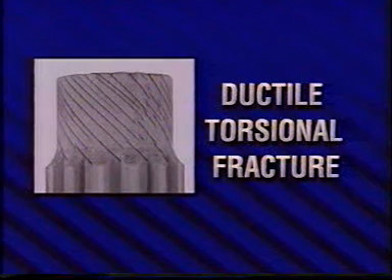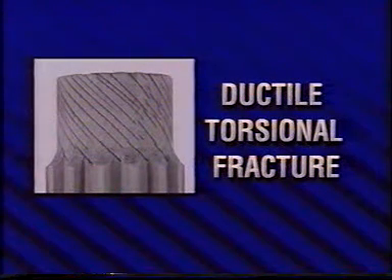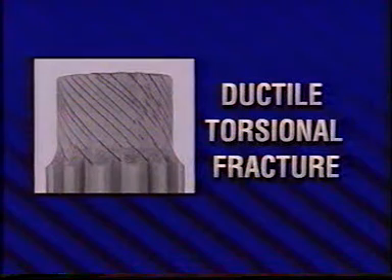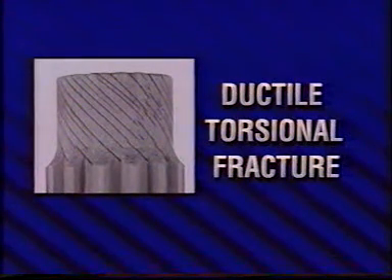Shear stresses are longitudinal and transverse. Each pair of stress components remains mutually perpendicular to each other. In a ductile metal subjected to torsion, fracture begins with elastic, then plastic deformation. Shear stresses exceed the shear strength of the metal.